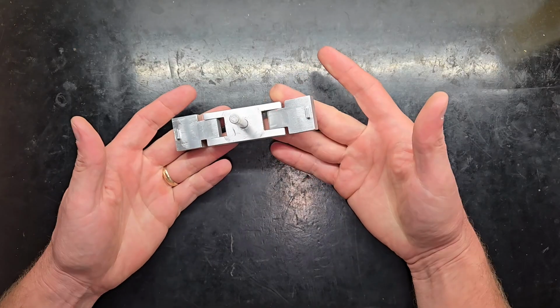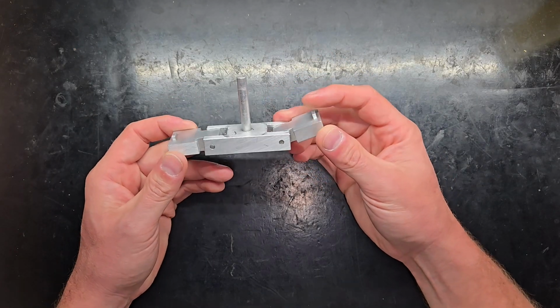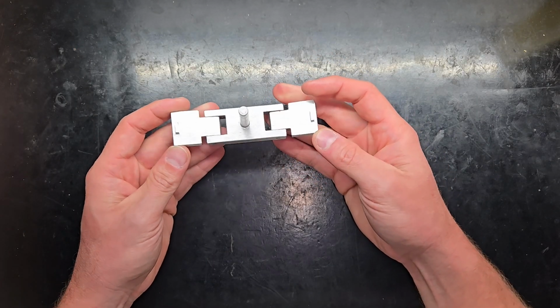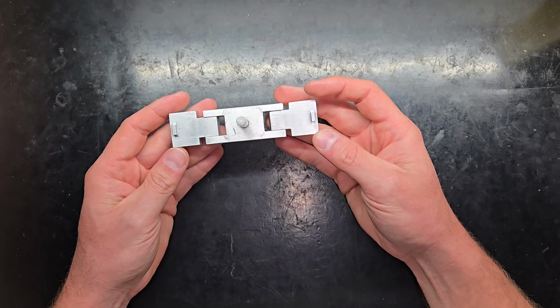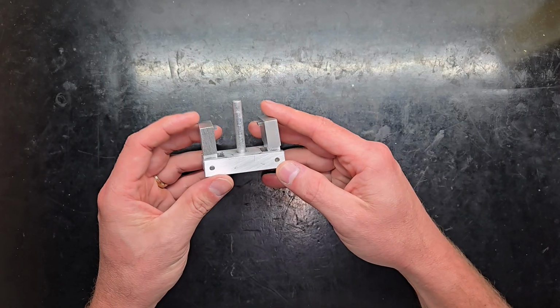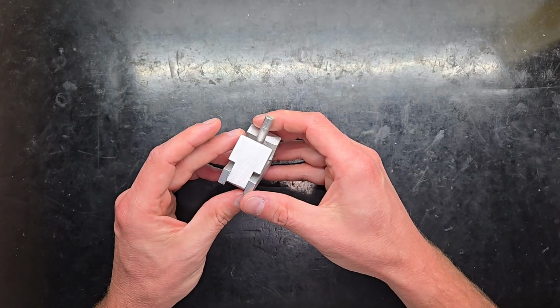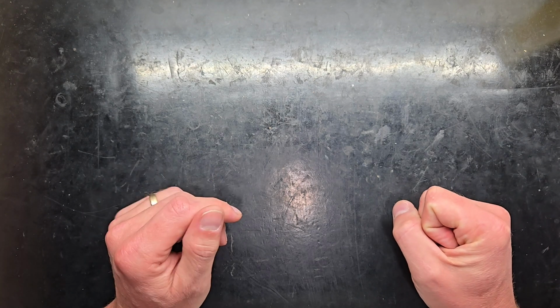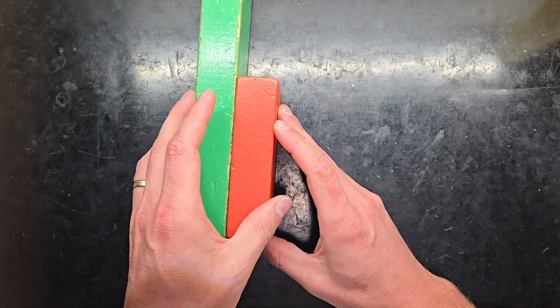Wear is the next thing we're going to talk about. Wear is the removal of material that is unintentional. The unintentional is important because here we have one of my MP5 mag tools. We removed material to get the shape, form, and function that we need for the mag tool to work, and most people would not refer to a machining operation as wear. So the four common types of wear are abrasive wear, adhesive wear, corrosive wear, and surface fatigue.